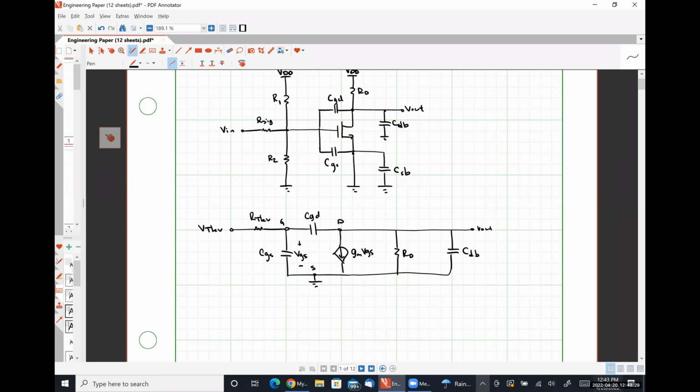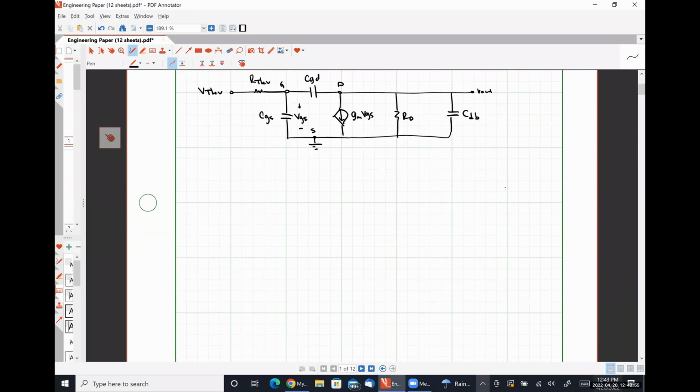So if we have a known transfer function between the gate and drain, with that impedance not being there, we can use that known quantity to divide our capacitor or our feedback element into two distinct impedances based on a certain set of rules. So let's define those rules by talking about Miller's theorem.